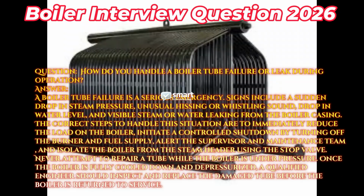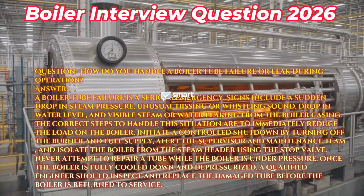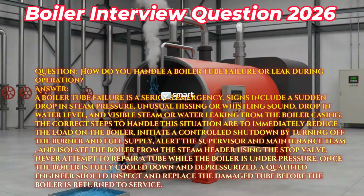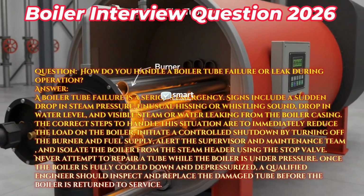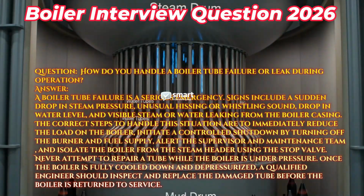The correct steps to handle this situation are to immediately reduce the load on the boiler, initiate a controlled shutdown by turning off the burner and fuel supply, alert the supervisor and maintenance team, and isolate the boiler from the steam header using the stop valve. Never attempt to repair a tube while the boiler is under pressure. Once the boiler is fully cooled down and depressurized, a qualified engineer should inspect and replace the damaged tube before the boiler is returned to service.